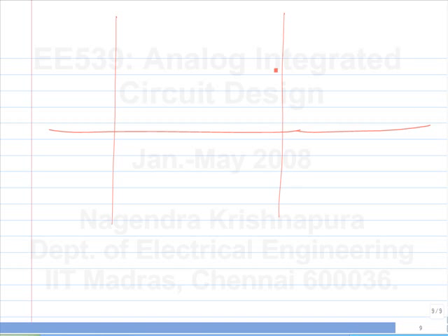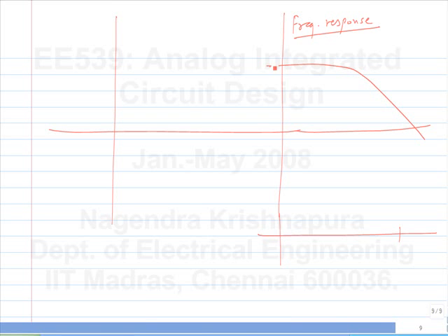So let's say this is the frequency response of an amplifier. Okay. Now, if you have complex conjugate poles at certain frequency, the system rings at that frequency, right? Okay. So firstly, what does this frequency response mean? This frequency response means that if you apply a sinusoid at this frequency, you will get this times that sinusoid and so on. Yeah. So now, if you have complex conjugate poles, the natural response of the system is to ring at that frequency. Okay.